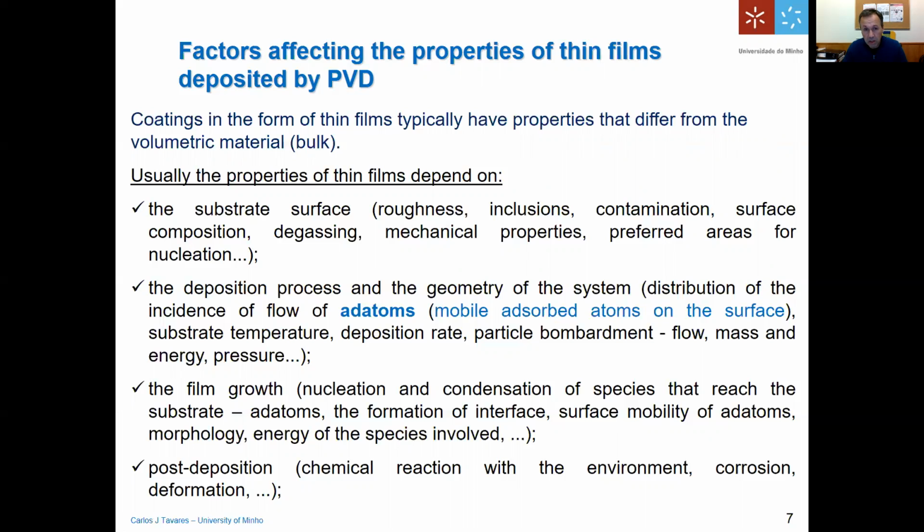So it's 1,000 million times less than atmospheric pressure. And if you put inside this vacuum chamber materials which will release gases, that will degas, then you will inevitably increase the pressure inside the system, and you will worsen the vacuum that you have obtained.